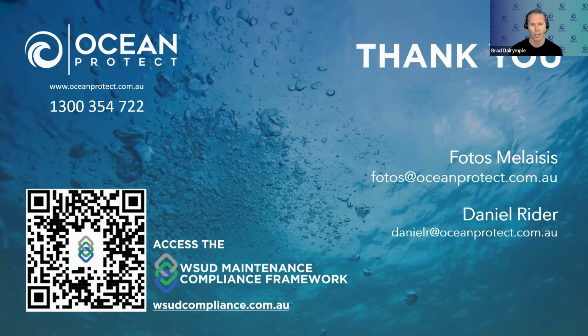But I think the key thing that is always forgotten, and I hate to say this, is that it depends. A bioretention system, for example, that's small on the outskirts of Toowoomba is going to be very different in terms of costs relative to the same system right in the Brisbane CBD. As Photos can attest, one of the biggest dramas is just access, travel time, etc. So fundamentally, if there are guides available, they should be used with caution. Overwhelmingly, unless you're getting it from a maintenance contractor, maintenance cost estimates are generally inaccurate, unfortunately.